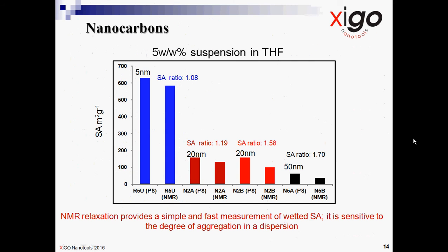The application performance of carbon black is determined by its nature, including how it is manufactured, and level of dispersion achieved. The particle size exerts the greatest influence on color. The finer the size, the darker will be the color. All carbon blacks contain aggregates that impact the surface area. A high surface area is associated with greater blackness and better, more uniform coating. Hence, aggregation needs to be kept to a minimum.